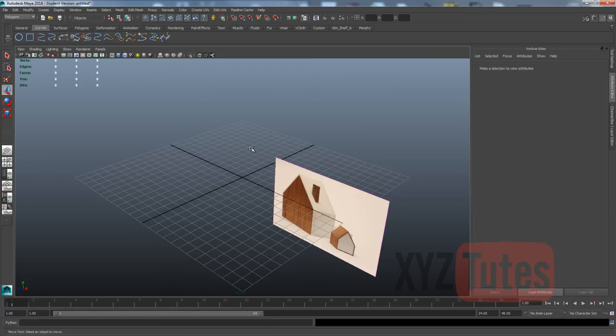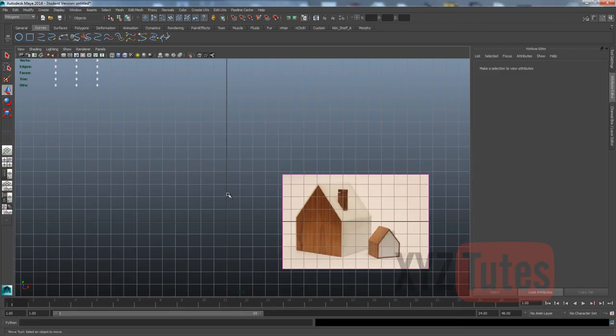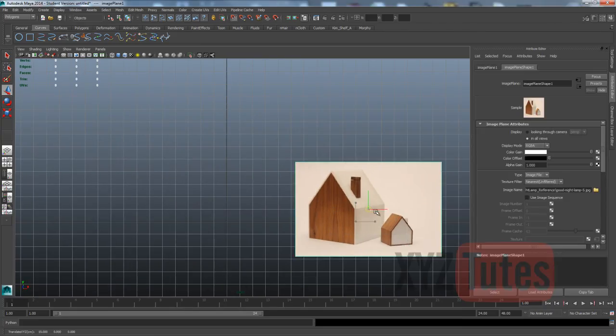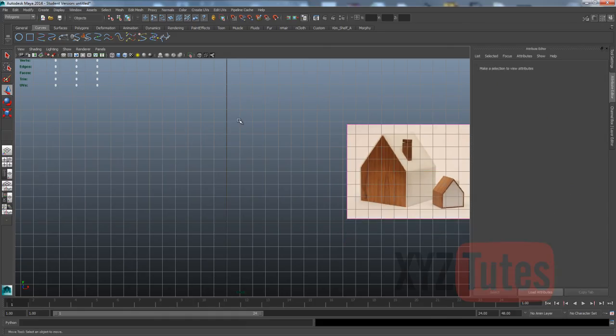So go into our front view now. Just click space, click on my front view, and we're going to construct the basic outline using some curves. So we'll change across to the different context menus that Maya's got for different things: animation, polygons, surfaces. We want to go to surfaces. The shortcut for that is F4, and then surface mode.